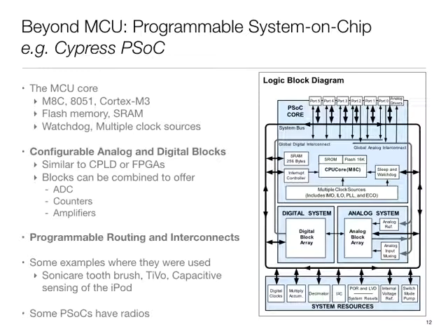It comes at a cost because my wires are no longer as efficient. So they burn more energy. So FPGAs are going to be slower and burn more energy, but still much better than doing the computation on the processor core. So these kind of chips, there's a company called Cypress which makes programmable SoCs, but they're not the only one. There are a lot of other companies which make such chips.